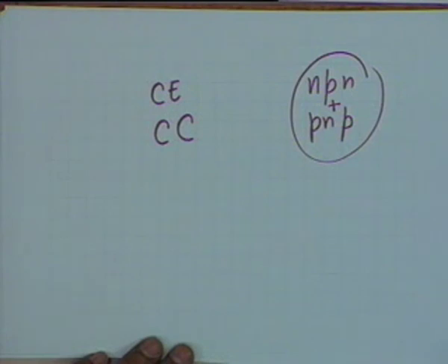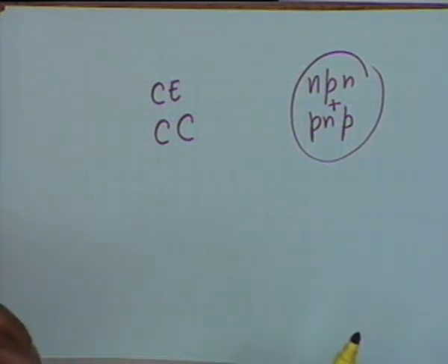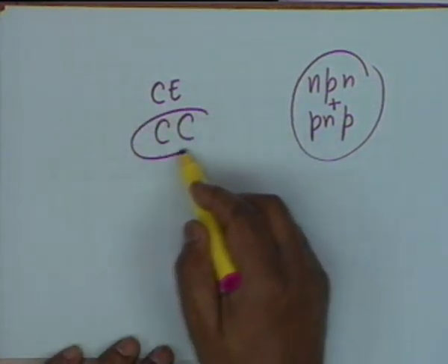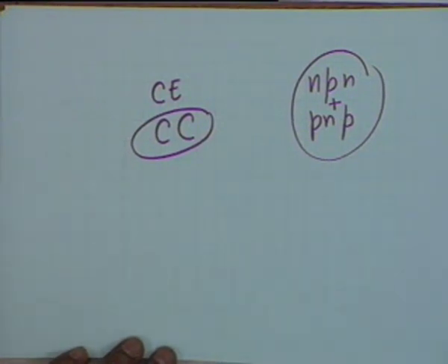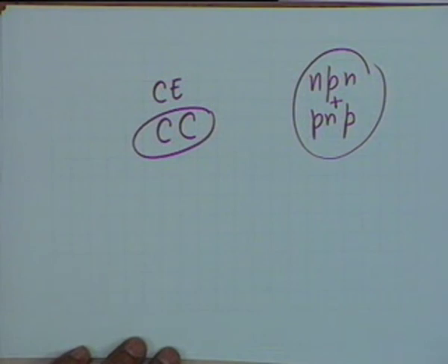This circuit uses what is known as, well, you have known common emitter amplifier. The circuit uses common collector stages, that is, each of these stages, NPN and PNP stage, which are connected in a push pull configuration, they are, instead of CE, they are CC. That means the collector is common between input and output.